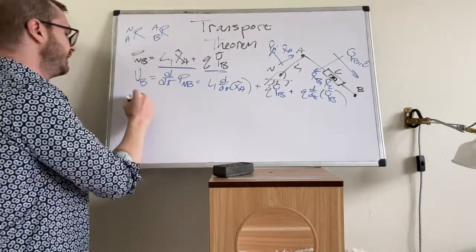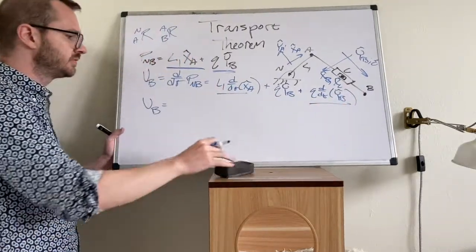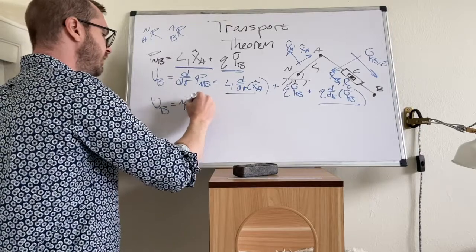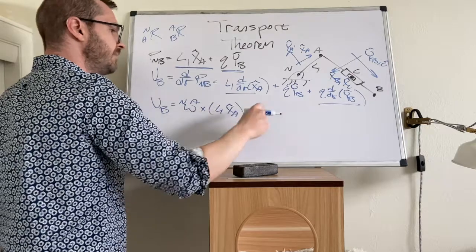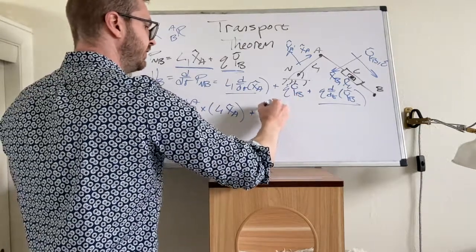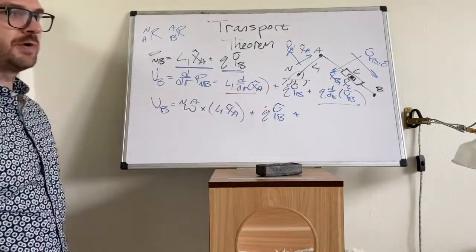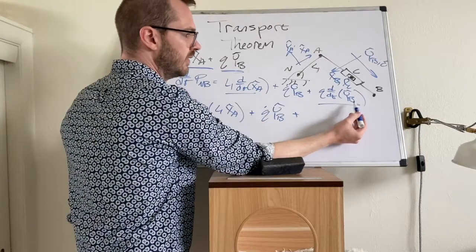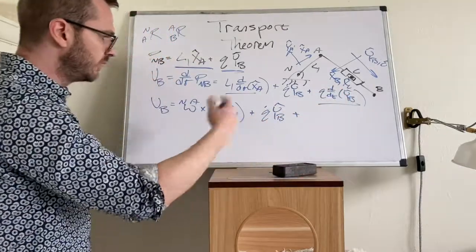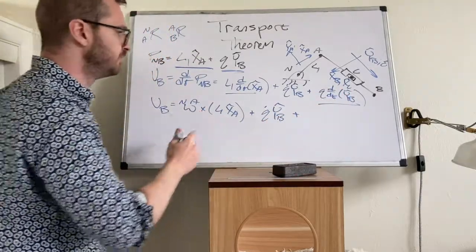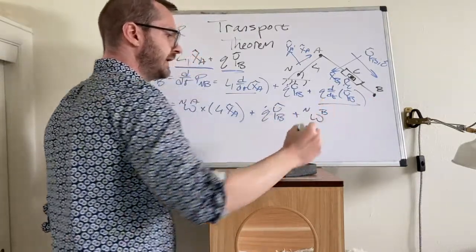Next, VB is equal to, we're going to take these terms and replace them with transport theorem, just like we did before. Omega in A cross, bring down that original position vector, L1 x hat A. Bring down this scalar derivative, Q dot. All right, we want to do transport theorem on that term down there. We're no longer taking ddt of x. Now we're taking ddt of y. How does that change? What does it affect? We're still going to use omega. We're taking ddt of the B frame, and it's omega into B.